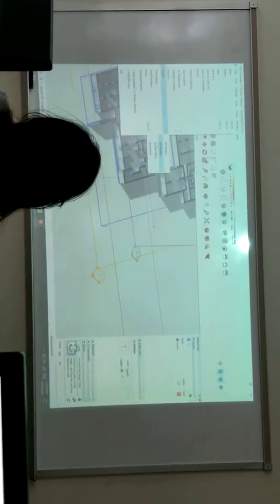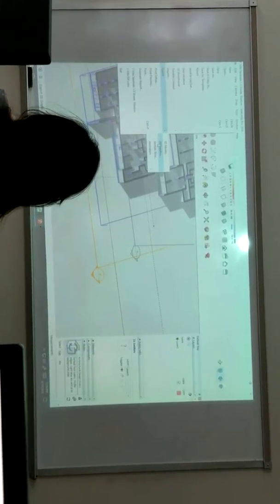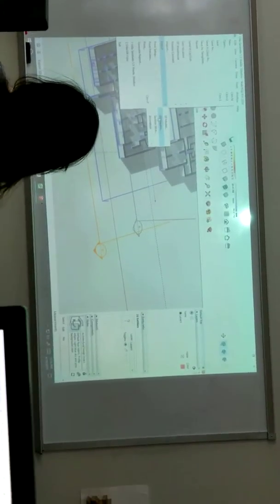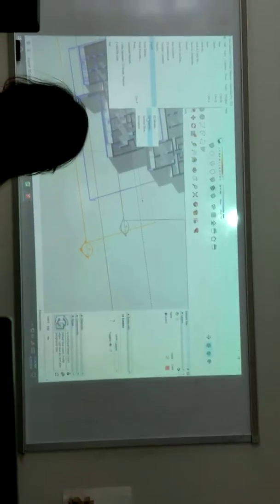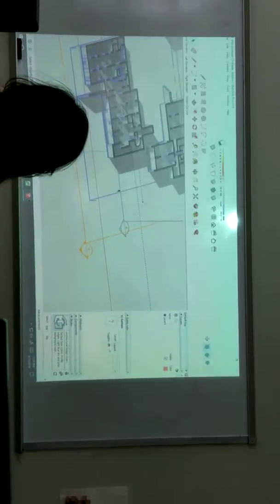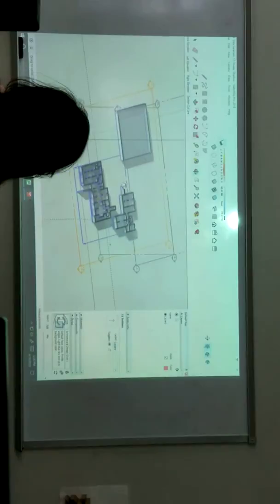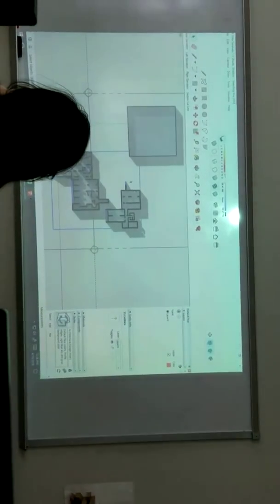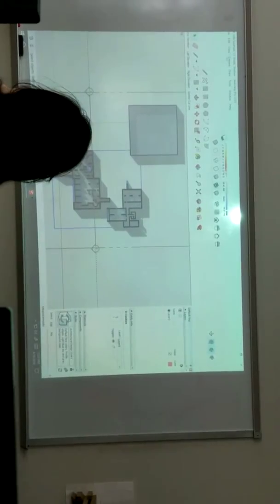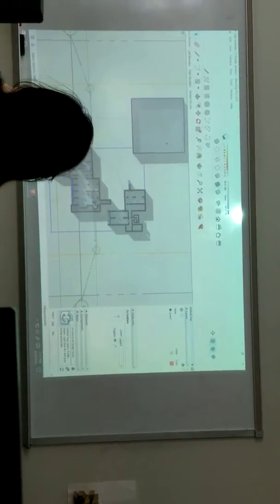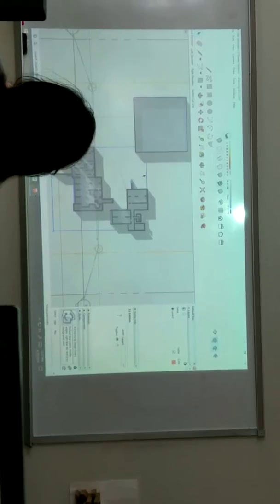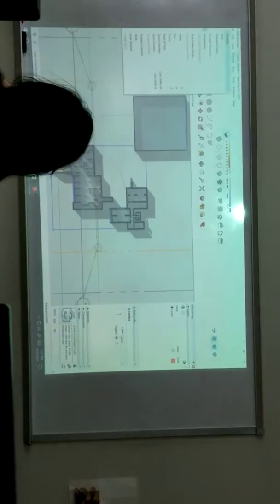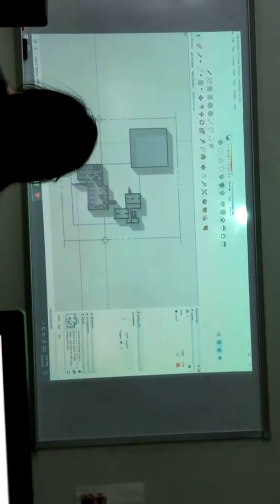Export, 2D Graphic. That's really important to say. SketchUp doesn't know do you want it as 3D, because they can do a 3D DWG file. I don't want that. I want a 2D DWG file. But before I do that, I have to go to my plan view. I almost forgot. Plan view, I'm in the plan view. Luckily, parallel projection is already on, but if not, if it's in perspective, that's not how I want it. It's not orthogonal, okay? So what I'm going to do instead is go to the camera, parallel projection,